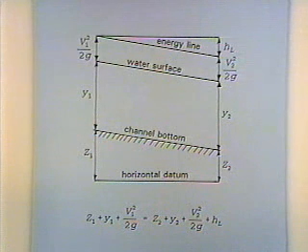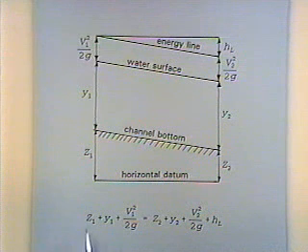Okay, we were just making the point that water surface profile computations are quite common. And what we want to do now is look at the basic hydraulics of how to do them. And the basic concept is the energy equation. And we used the energy equation last week in pressure conduit flow. We'll use the same old energy equation in open channel hydraulics as well. It looks a little different though. We write it this way.